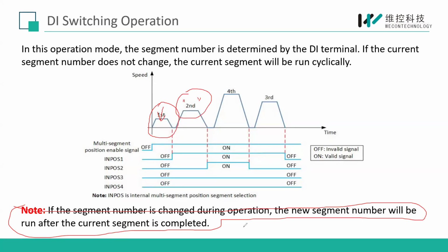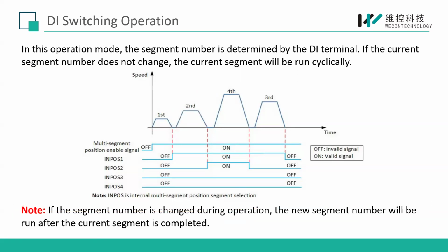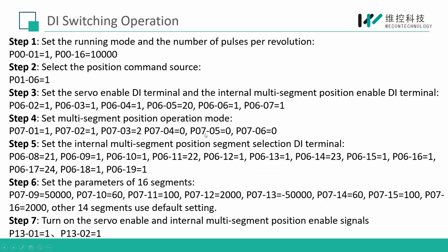So you can see the change of DI status will not take effect immediately. It will take effect after the current segment is finished.